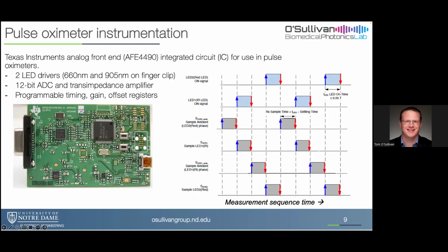But the instrumentation is relatively simple. I won't dwell on this, but you can buy chips from Texas Instruments and other manufacturers that have LED drivers built into them. This is just one example, this AFE4490. It'll drive two LEDs.